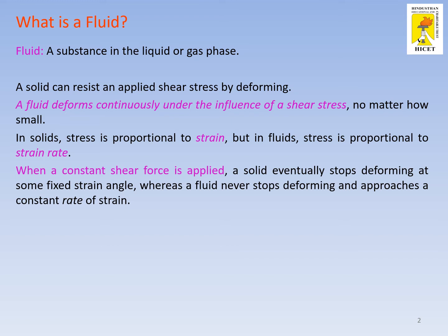The basic distinction between solids and fluids is a very important one. A solid can resist an applied shear stress by deforming. A fluid deforms continuously under the influence of shear stress, no matter how small the shear stress is. In solids, stress is proportional to the strain, but in fluids, stress is proportional to strain rate.